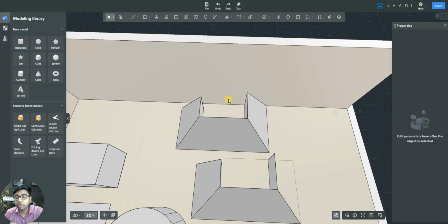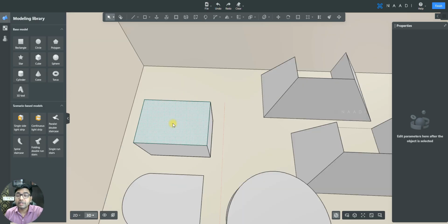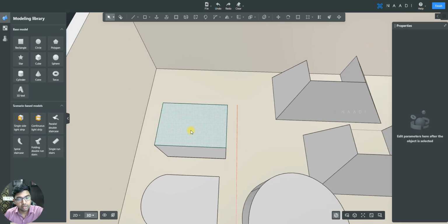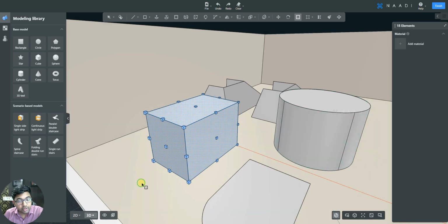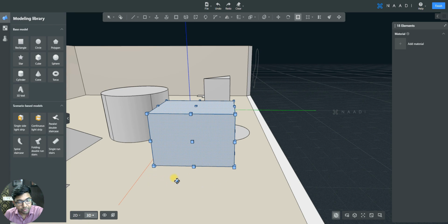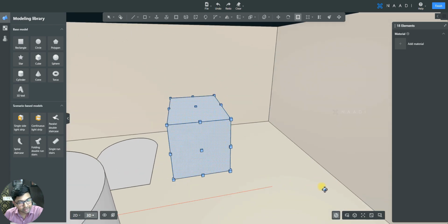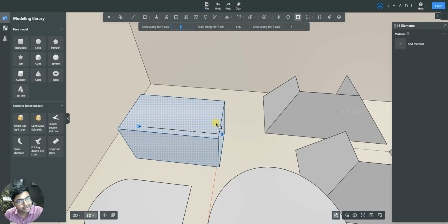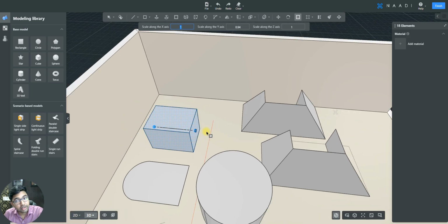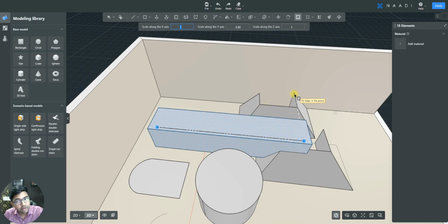And the next important basic modification tool is your scale tool, using which you'll be able to scale a surface or a group to your preference. So in this case here, let me just select this cuboid. And now if I want to scale it up, can you see? There is this scale tool here which is present right next to the rotate. Just click it and you will see these pick toggles on all the surfaces of this cuboid, right? Using this, you will be able to scale it on a specific axis. So in my case here, if I want to scale this cuboid from this side, just click on the center point of that toggle and stretch it manually. Can you see here? Or if I want to just stretch it based on another reference, I could even place my cursor on the reference points here so that the component will be stretched to that extent. Can you see?